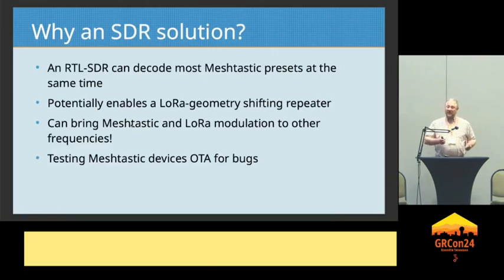So why an SDR solution? Well, Meshtastic and the Semtech hardware only supports, I call it a geometry, but it only supports one spread factor, one code rate, one frequency, and one center at a time. You can't really hop, and it takes time to hop those frequencies.